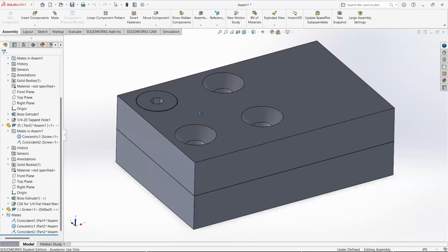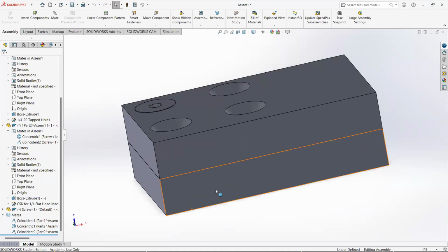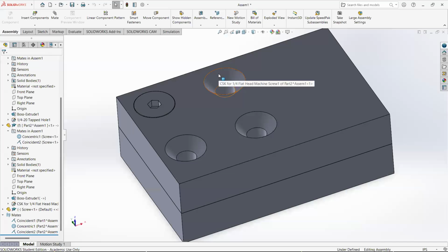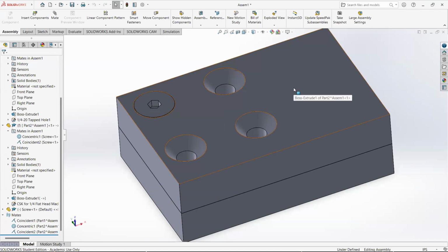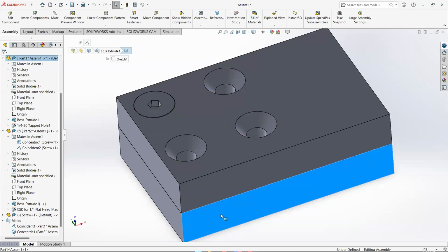And again, overall, if I change this base plate, everything above it cascades, and rather than having to remachine one part, or at least having the trigger to look and see what changed, because if I make a change and don't know about these in-context parts, that can really be a problem as far as revision control, and just plain not having parts work that are in the middle of an assembly when physical parts at the bottom change, but I forget to change the parts in the middle.